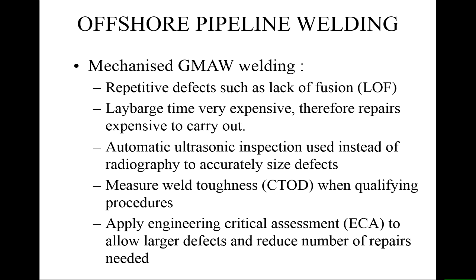So we use automated ultrasonic inspection instead of radiography, because we want to size defects so that we can make a decision using fitness for purpose standards about whether we actually repair. And sometimes when you qualify the welds, you measure weld toughness using crack tip opening displacement methods, which are not usually specified for onshore, to really make sure that this is going to be an okay welding process.